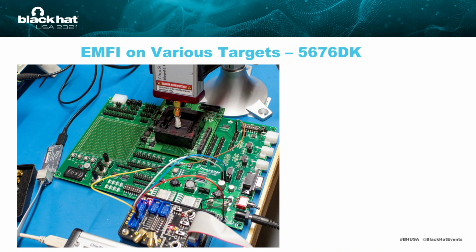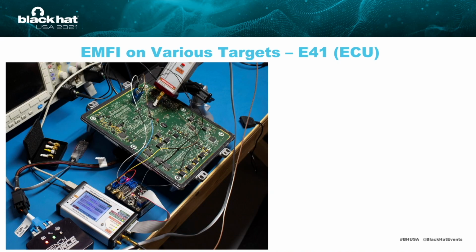This is interesting because this would mean this is the type of board that a developer would use. We also had the actual ECU. So this is the ECU pulled from a car, so you can see the microcontrollers on there. And I have some test points attached to it at various spots. So I basically have the serial console going to a chip, so I clip onto that. There are some pads with the reset pins and stuff like that.